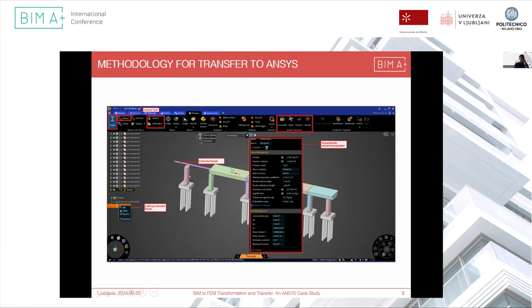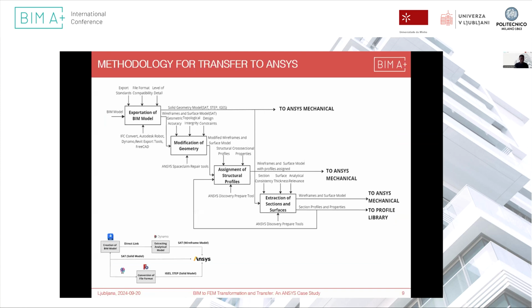So there is a need to fix these gaps, and there are several tools within ANSYS Discovery and also ANSYS SpaceClaim which help to repair the geometry. This applied to the lines and surfaces model, whereas in the solid model imported into ANSYS, there are also other tools that were used to check if there are repeated surfaces or repeated lines, which would be a problem when generating meshes in ANSYS Mechanical.